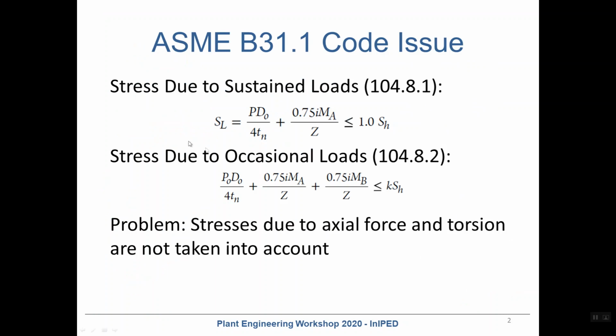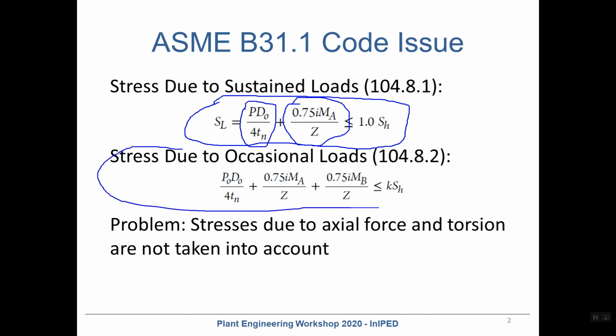Let's check this equation from the code and have a look at it. We will see that it includes the axial stress from the pressure and the bending stress from the bending moment, but it doesn't include the stress caused by axial force. The same issue applies to occasional loads. It doesn't include the axial load stresses.